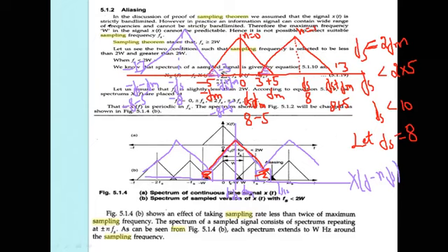It is fully recovered from its samples if the sampling rate Fs is greater than or equal to 2Fm only. When Fs is less than 2Fm, it is not recovered, because of aliasing. Understood, my dear students? From the examination point of view, how can we avoid aliasing? We take Fs greater than or equal to 2Fm. If aliasing occurs after sampling, how can we rectify it? By using Fs greater than or equal to 2Fm only.